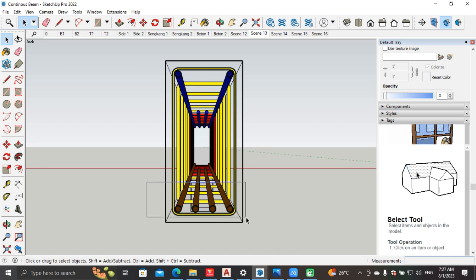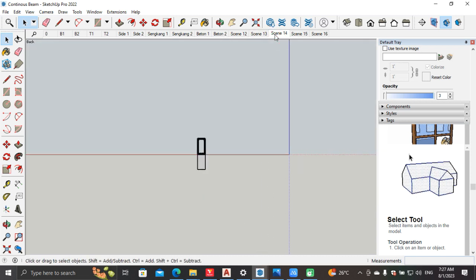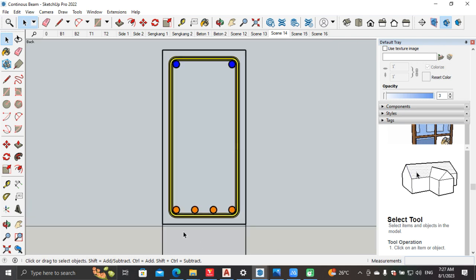There are 4 numbers of bars. Here you have cut all the 4 parts, and here you have cut the 2 parts. That is just for keeping the neat structure. We have extended this 2 portion. If this is also coming, it will cut that also. And what happens to the sectional diagram? It comes like this. That is, we have cut the 4 bars at the bottom.